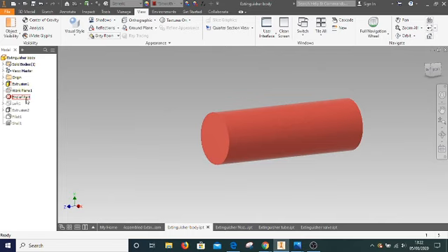And on that work plane I then created a circle which allowed me to sketch that profile and then loft this part from here to here. Finally, I extruded that 50mm diameter circle a further 30mm to give me the neck of the bottle.